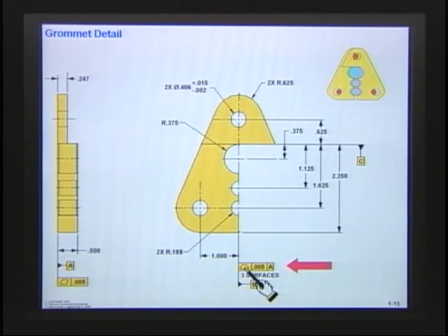So by putting a profile on, I have a tolerance zone, and a tolerance zone is a band of tolerance. Let's see if I can draw that band of tolerance here. It says that I have a perpendicularity zone, and the perpendicularity zones are in line. So I'll show that tolerance zone, it's kind of hard to see there, but there's my tolerance zone. I have a band of tolerance, and the surfaces then have to fall someplace inside of that zone.